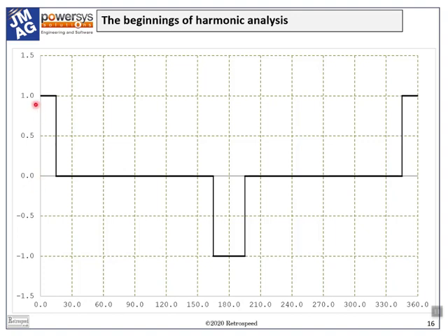This could refer to coils 1 and minus 7, one of which produces a rectangular pulse of MMF and the other one a similar rectangular pulse of MMF 180 mechanical degrees away. This is mechanical degrees along the bottom. The width of each of these so-called pulses is 30 mechanical degrees, which is the angle between the center lines of the slot openings on either side of each coil. That is the slot pitch angle.